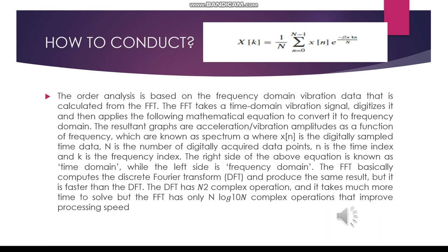This slide is about how to conduct the data analysis and fault diagnosis on shaft. So the formula has been placed at the top of this slide. The order analysis is based on the frequency domain vibration data that is calculated from the FFT. The FFT takes a time domain vibration signal, digitizes it, and then applies the following mathematical equation to convert it